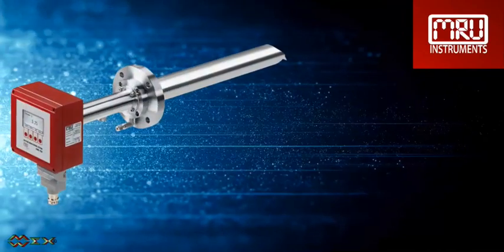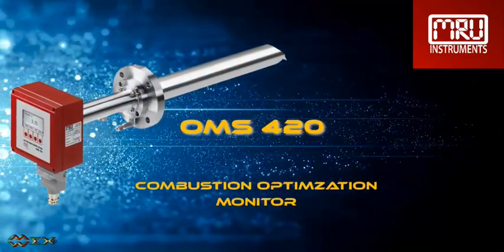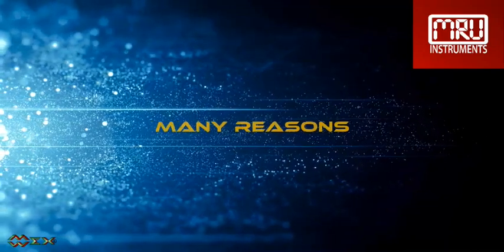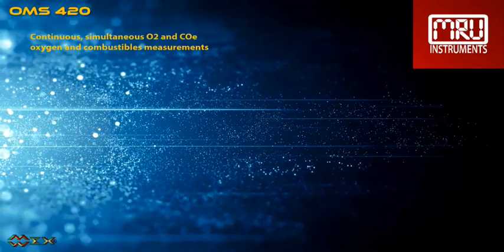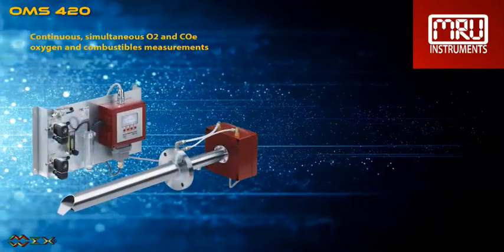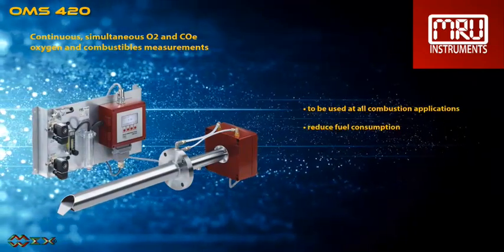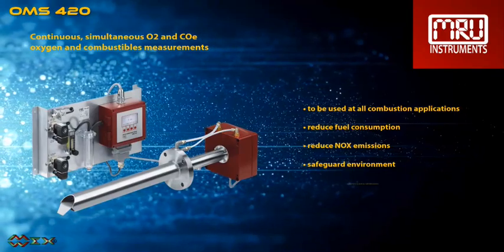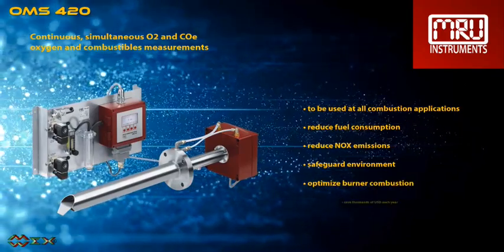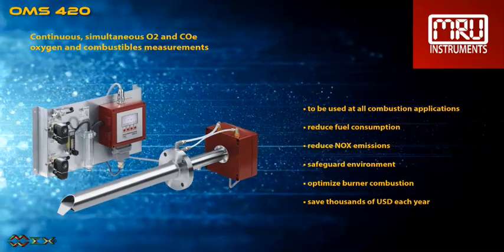Today we are having a look at the IN-SITU O2 and COe Monitor, Combustion Optimization Monitor. There are many reasons to use an OMS 420. These monitors measure continuously and simultaneously oxygen and combustibles, and are used at all combustion applications, reducing fuel consumption, reducing NOx emissions, safeguarding the environment, optimizing burner combustion, and saving thousands of dollars each year.